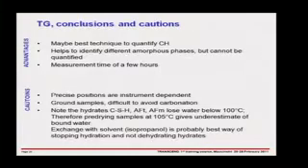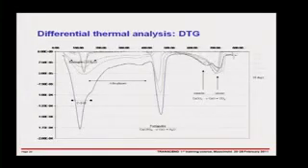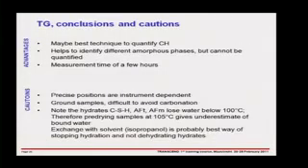So, just to summarize that technique, it's very good to quantify calcium hydroxide. It gives you a rough idea about different amorphous phases, but it's difficult to quantify. Incidentally, going back to the effect of temperature, we can see that the effect of temperature actually does very dramatically change the amount of water bound in the CSH we see in this peak here. That's something we're still looking into. It's relatively convenient. Each scan takes a few hours.